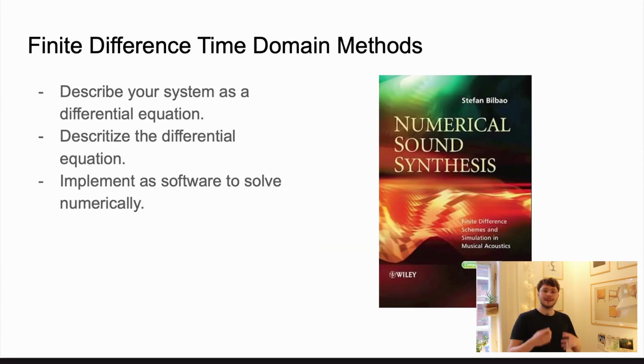So we wanted to recreate this sound digitally, and the method we chose to do so is finite difference time domain methods. In this method you describe your system as a differential equation, you then discretize that equation, and you then implement it as software so that you may solve it numerically. A really good resource for this topic is Numerical Sound Synthesis by Stefan Bilbao, which is also where you will find most of the sub-models used in this project.